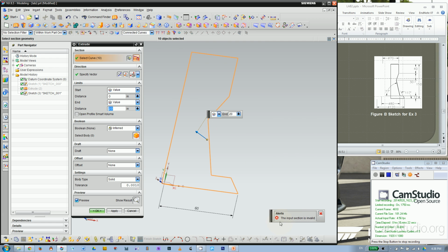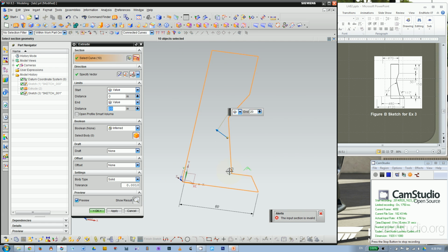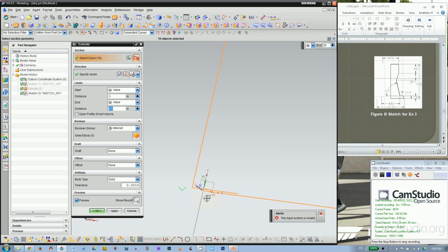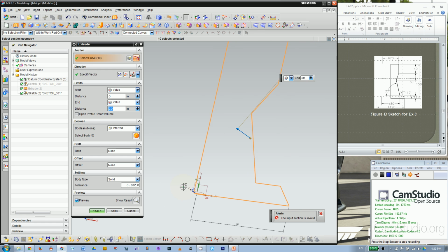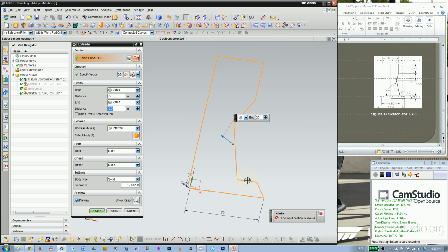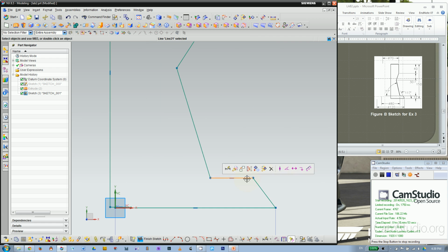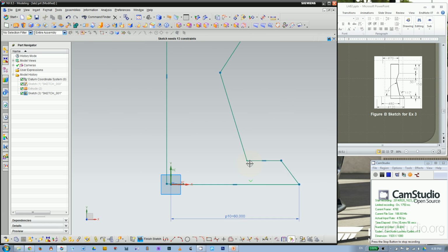You have two possibilities. One is like here, we have two lines on top of each other. It's not a closed loop because you have overlapping. And the other possibility is like this little gap. But sometimes for the gaps, you can actually extrude them into sheet body. But overlapping is the worst. You will always get this. So you always want to examine your sketch.